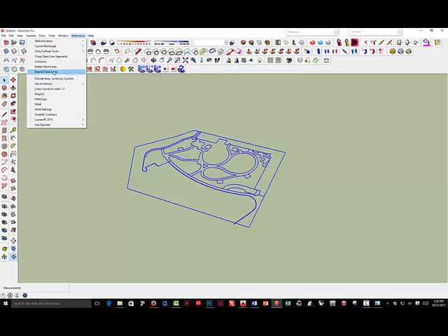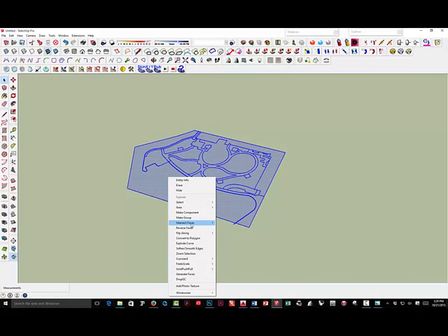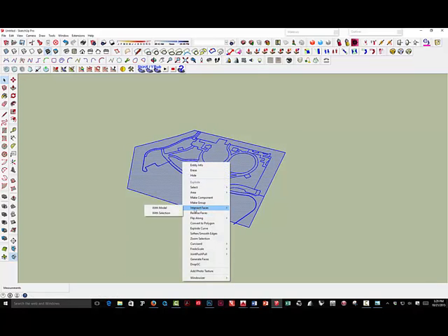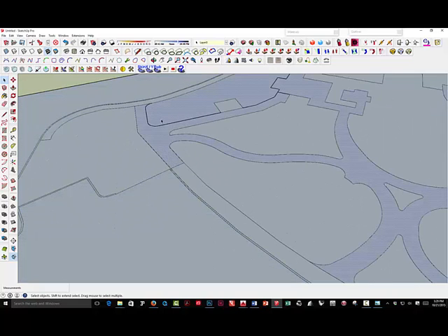Even now I can do, let's do Extend Close Lines. All right, and now let's right-click on it. Actually, it's better to do it in that sequence, and choose Generate Faces. Select it all, right-click, Intersect Faces with Selection. Get it again, just try it again. Okay, that's a lot better. Got a little break there, but it's better.